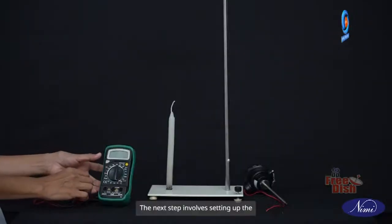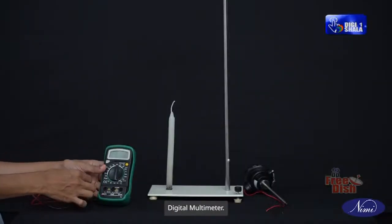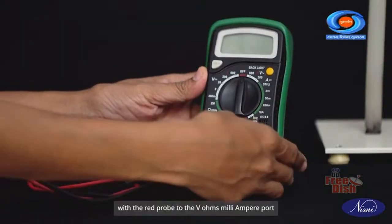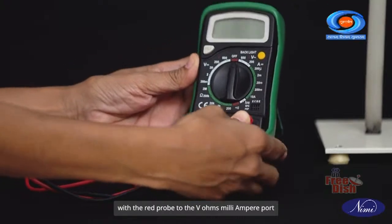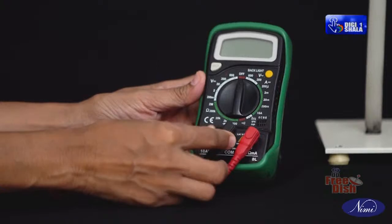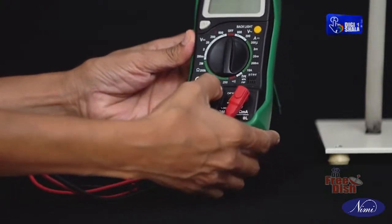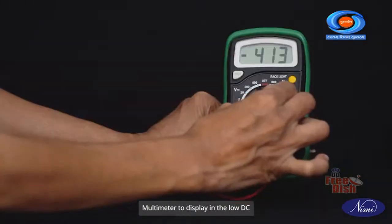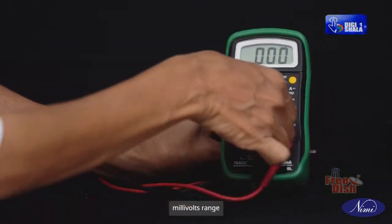The next step involves setting up the digital multimeter. Connect the wires in the correct polarity with the red probe to the V ohms milliampere port and the black probe to the common ground, that is COM. Then select the mode on the digital multimeter to display in the low DC millivolts range.